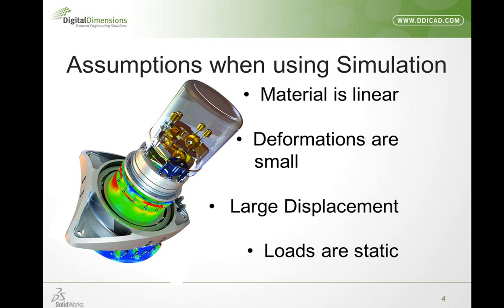So luckily the solver has a checker that will decide whether your deformations are small. If the deformation is not small, then the software will give you large displacement feedback. We do have a mode called a large displacement mode, which I believe we pointed out in the previous webcast, but I do want to point this out once again. This large displacement mode is pretty much a fudge factor that will give you a ballpark answer to a nonlinear setup. So for our particular assumptions, we're going to assume that all of our deformations are small.